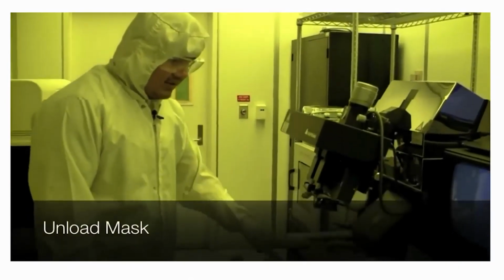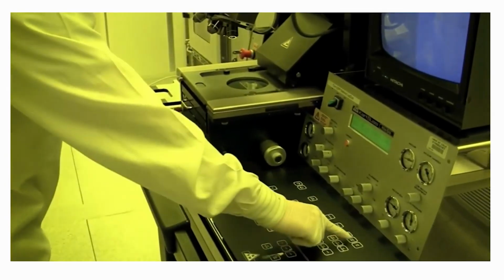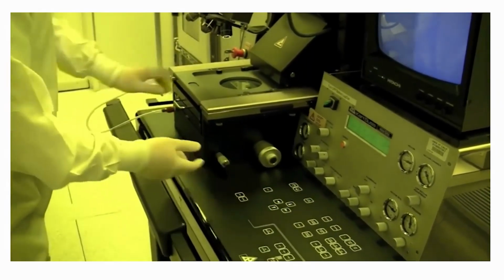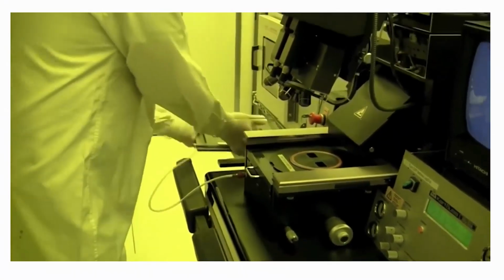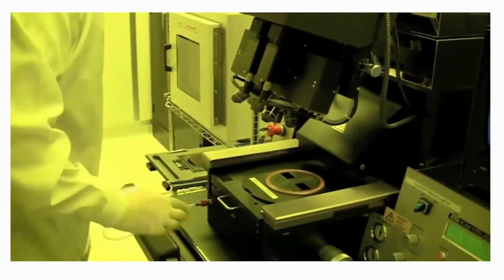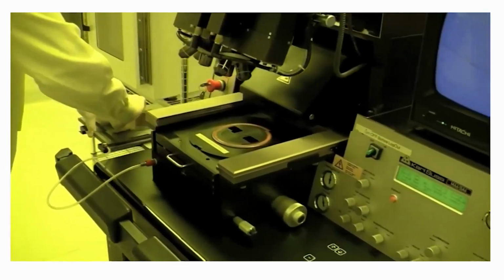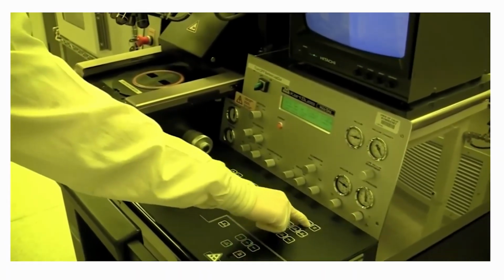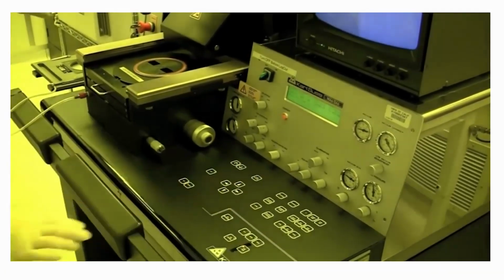If we want to unload a mask, we press the change mask. It's pretty similar to loading it. It's a reverse process. You would press change mask, you would take your substrate out, you would hit the enter button to remove the vacuum, and then you would take your mask out. You would press the change mask button again, and it would confirm with enter that you know the mask is there.